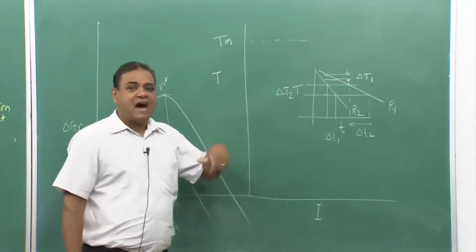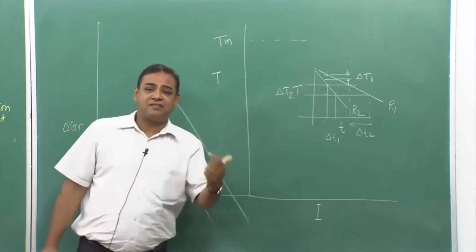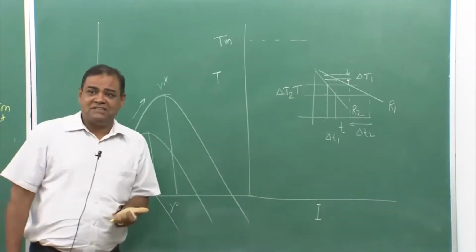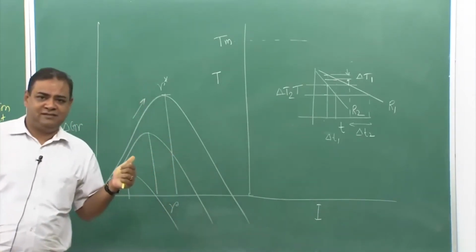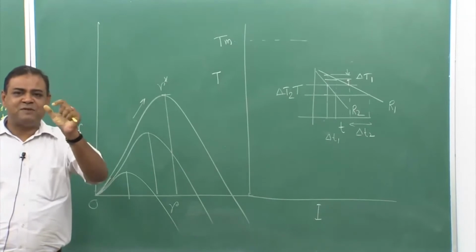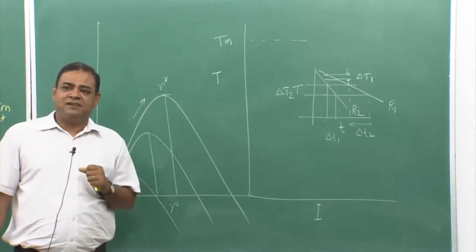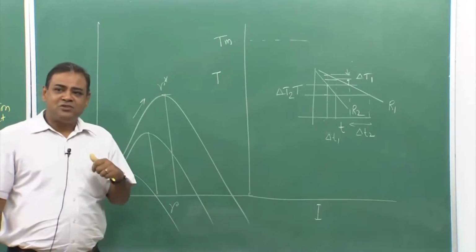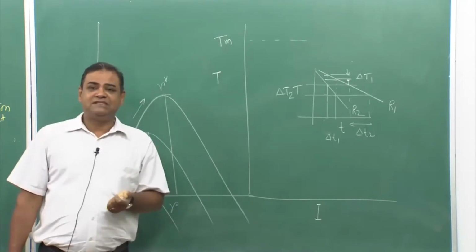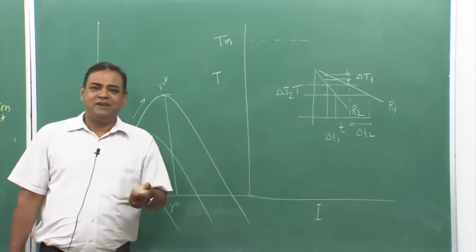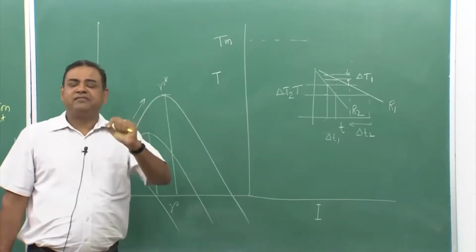Now, if I get higher cooling rate, I am getting higher del T, that means my R star would also decrease. It suggests that I might get finer structure. The size of the sphere would be finer and finer, and I would get very, very fine structure. So, that also gives little idea why increase in cooling rate during steel heat treatment gets me very, very fine pearlite, or very fine grain size.